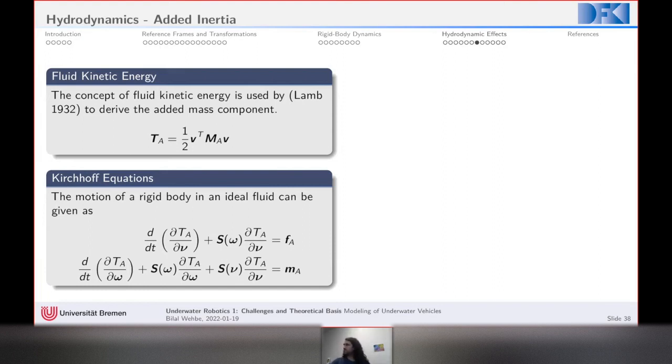So can we simplify the vehicle shape as a cuboid, a parallelepiped, to calculate the added mass? Yes, exactly. This is what we usually do to calculate that. We simplify those geometries, or we take a complex geometry and approximate it as a combination of different simple geometries. However, it's not so accurate, and I can tell you that. The better way, if it's feasible, if your vehicle is not so huge or not so expensive to put in the water, is to collect data and try to identify it. That is always the better approach. But yeah, this approach is also valid.